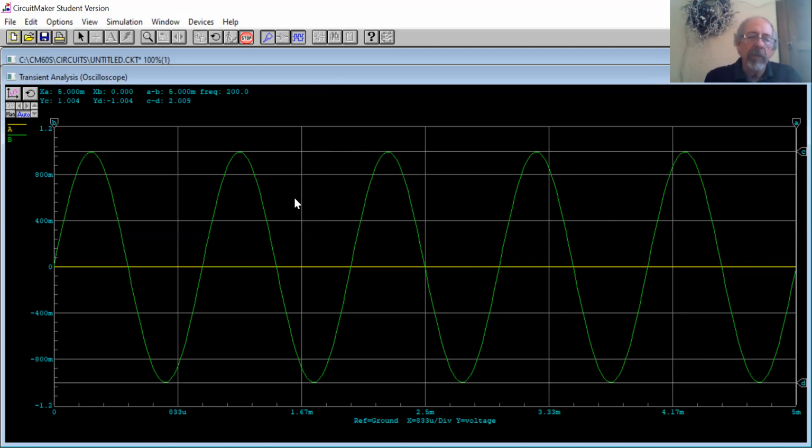One of the things will be that you look at phase angles, and it turns out that if I can see 2 traces on the scope of 2 sine waves, and I've got a capacitor or inductor in the circuit, what you'll discover is they won't lay on top of one another, they'll be phase shifted this way. And that's another valuable thing you could do with Circuit Maker. So I'm going to stop at this point.